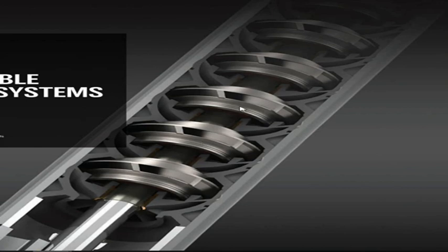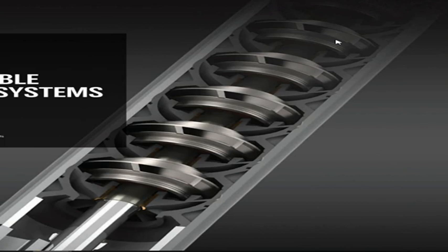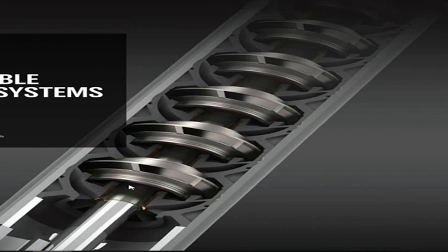and we install the stages in series fashion, or we stack all the stages. That is our whole ESP pump. This rod is connected to the motor downward and to the rotor of each stage. So when the motor rotates this rod, it will rotate every rotor inside each stage. That is basically the inside of an ESP.